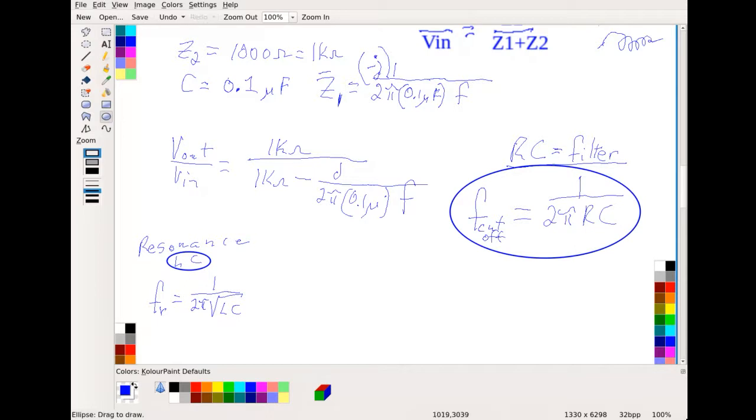So you get this cutoff frequency, which he just calls FC there in equation 22.16. It comes from what value of resistance did you choose, and what value of capacitor did you choose. By choosing those, we get this cutoff frequency.